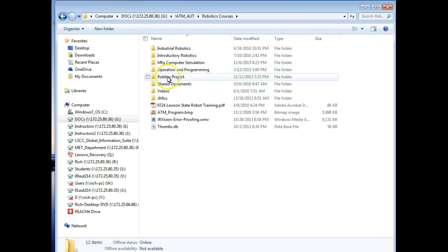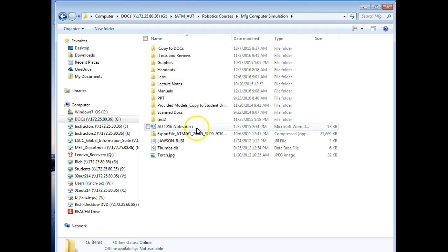Make a copy. Delete it off the controller, right? Come back here. You transfer it to your drive. And then modify it. Run it. Then modify it. And then take it back and upload it again. And then run it over there.